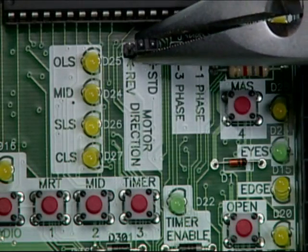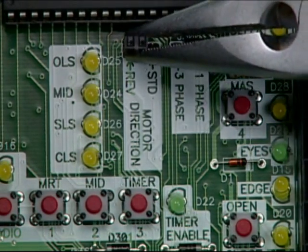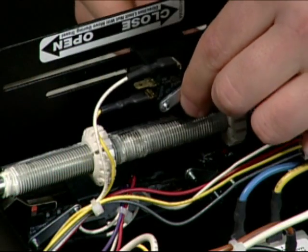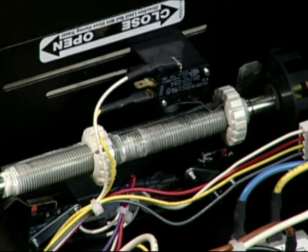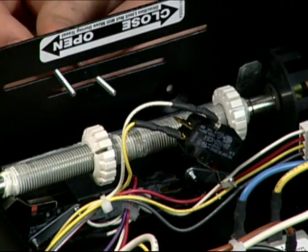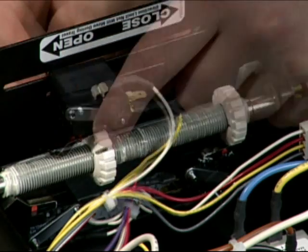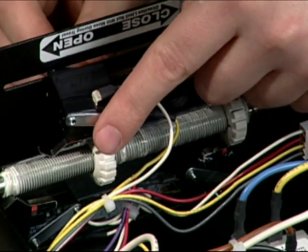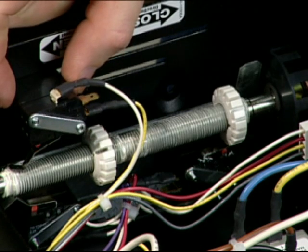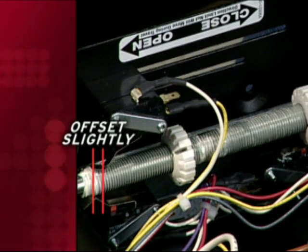With a pair of needle-nosed pliers, remove the black jumper and relocate it to either the standard or reverse motor position. Next, with a screwdriver, remove the screws from the safety limit switch. Remove the retaining bar and rotate the limit switch 180 degrees. Now, reattach the limit switch with the limit screws and the retaining bar and relocate to the opposite side of the limit shaft. The safety limit switch should be located so that it is slightly offset inside of the new close limit switch.